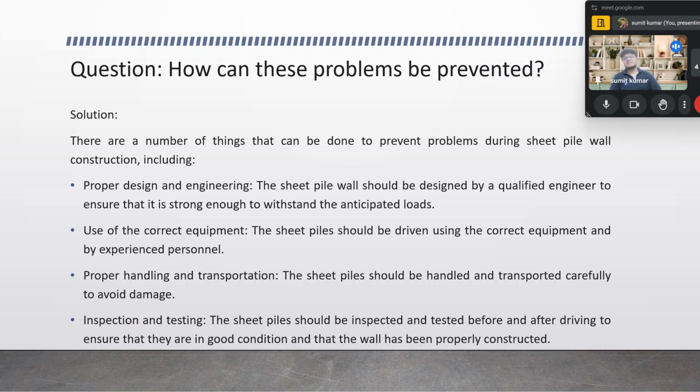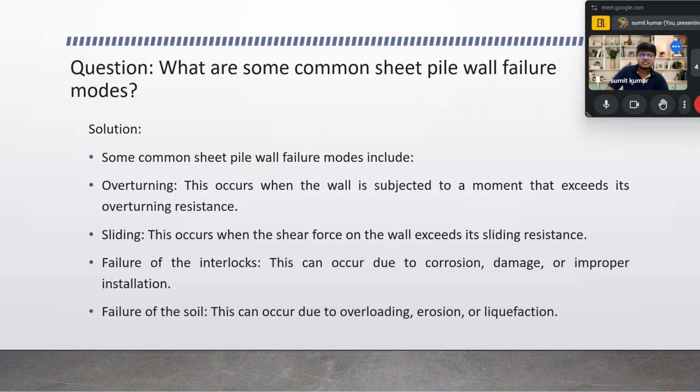The next one is inspection and testing. Whenever we take sheet piles for temporary construction, maybe like the steel sheet pile wall, inspection and testing should be required. That is, sheet piles should be inspected and tested before and after driving to ensure that they are in good condition, and that the wall has been properly constructed.